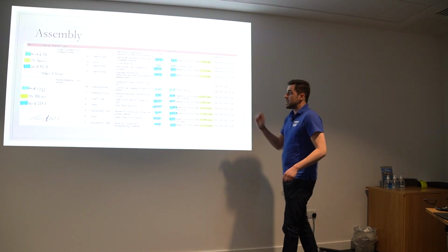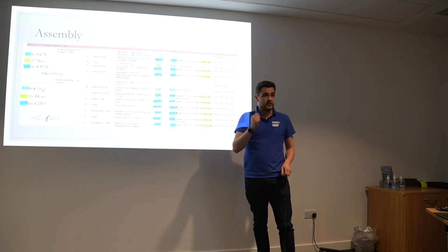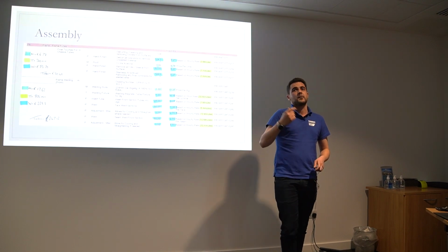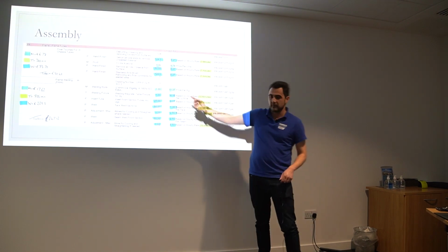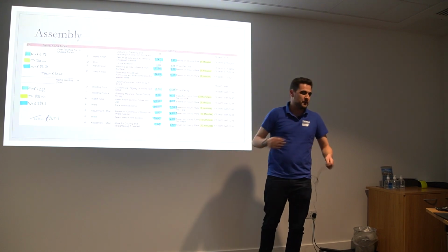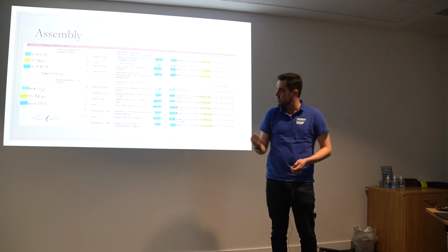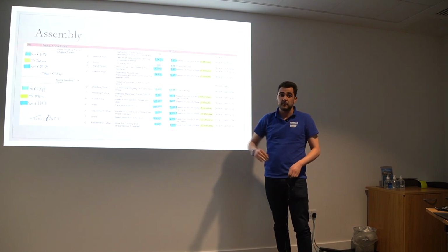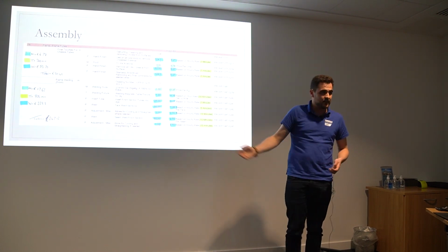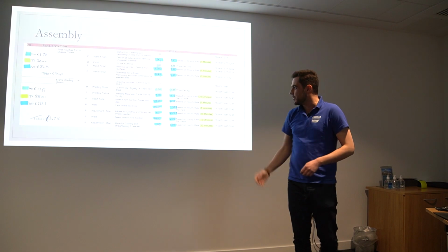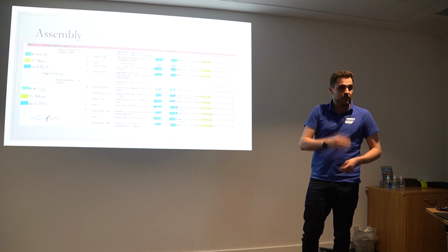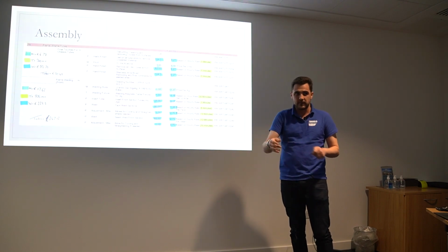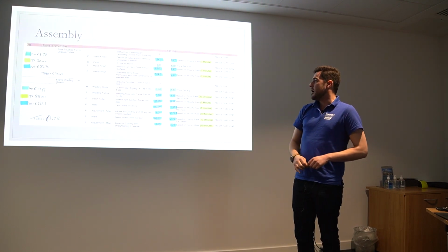The next bit as well is add your consumables into the detailed bill of materials and costed sections. We're not expecting you to go and make your own welding wire or your own nuts and bolts and washers, unless they're obviously specialist, but add them in. When you add up one chassis, you get through quite a bit of welding wire. When you have 100 chassis, you get through a lot of welding wire. So make sure you add that in and have your price per kilogram, price per length, whatever you're buying it in at, whatever your conversion rate is, add that in.